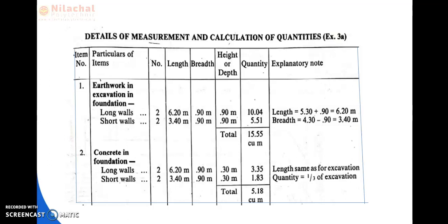Which one is the bottom part of the foundation? The bottom part of the foundation is the concrete in foundation. It is the first layer of foundation, so it is the bottom part of the foundation. So the excavation breadth we consider on the basis of the bottom part of the foundation.